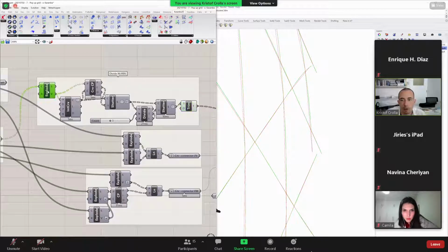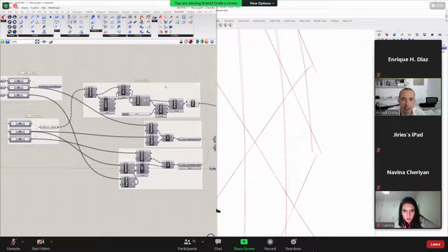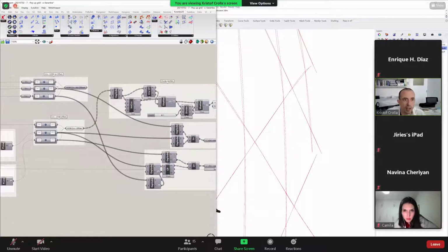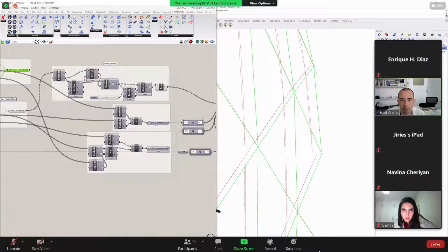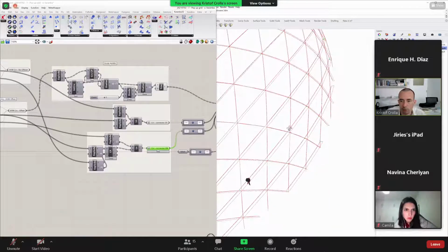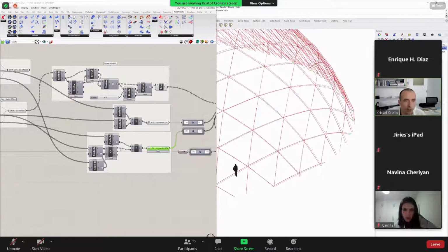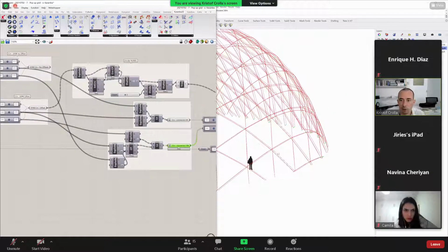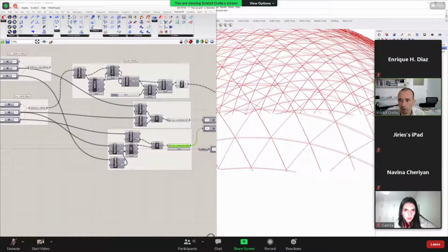So I'm getting my polyline points here. I'm first starting by drawing a NURBS curve through it, and then I'm just shattering each segment into smaller parts. Nothing too difficult there. Then I need to make my connectors. Because I have my original layer here and my final layer afterwards, it's just a matter of extracting the right vector points and adding those in. It's a little bit tricky sometimes in identifying, definitely for the diagonals, which points to go to, because sometimes,